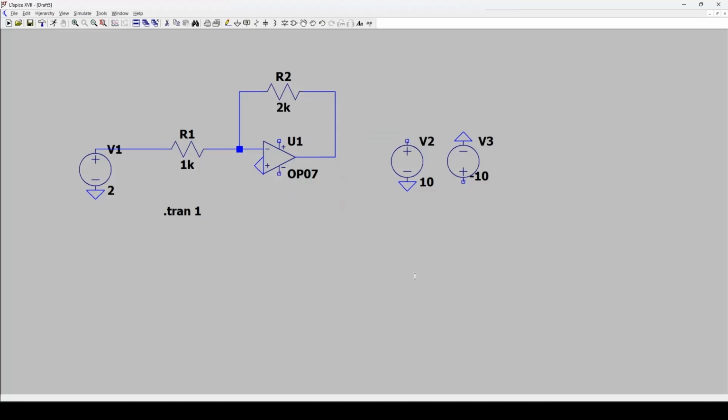And so we're going to introduce a concept of nets and labels. Net labels essentially allow us to connect components without using wires. And one thing to note here is that any component is going to be connected if they share the same net name. And so the name is actually very important here. And so I'm going to go to draft and then go to label net. And I'm going to type in V+ for positive voltage. And I'm going to connect it to my positive source.